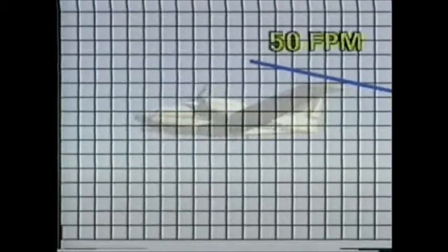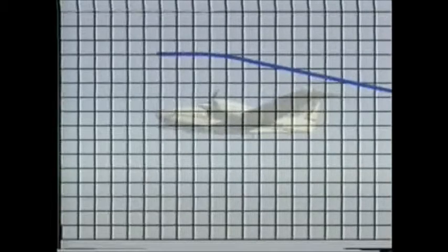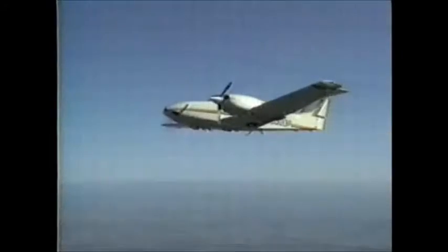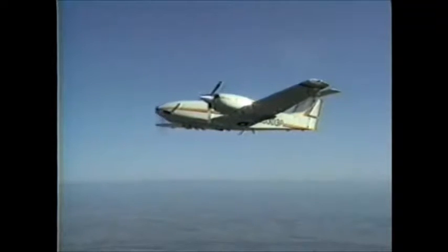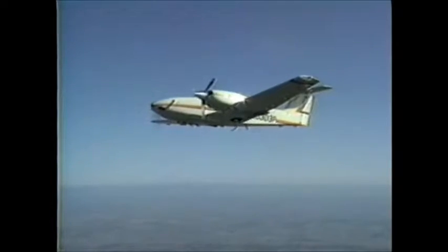This ceiling is the maximum density altitude at which VYSE will give you a 50 foot per minute rate of climb with one engine inoperative. The single-engine absolute ceiling is the maximum density altitude an airplane can reach and maintain on one engine. Now that we've discussed the theory of engine-out flight, let's look at some practical applications.